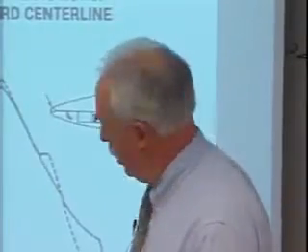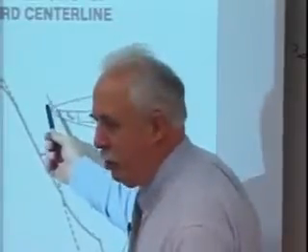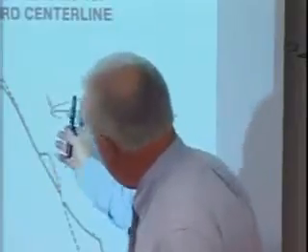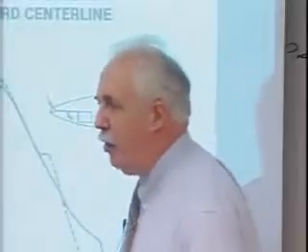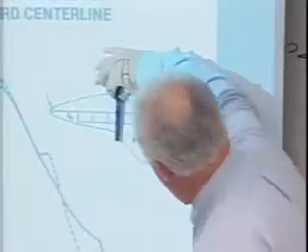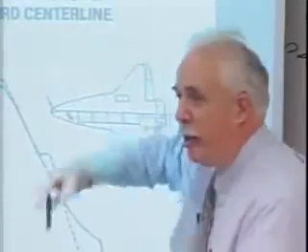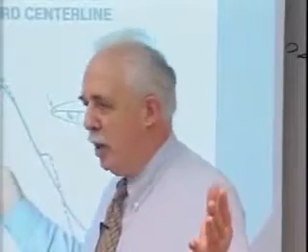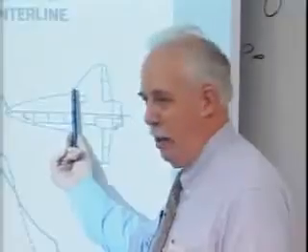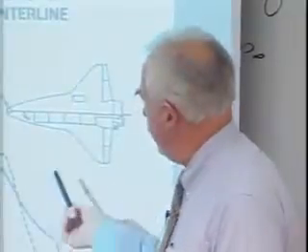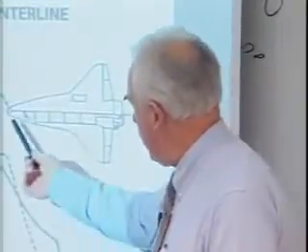Now, the flow field technology, we had a heck of a time getting from our starting solution, subsonic flow, which used one particular algorithm, to march supersonically down the vehicle. We succeeded in doing that prior to flying, and we were able to compute up to the point where the shocks from the wing intersect the shock from the fuselage, and then we had another subsonic region, and we weren't able to handle it. Now we can do that. But at the time we flew, we could only compute up to about here. Okay? Now, this is not what you'd see in the journal. I'll show you one you'd see in the journal here in the middle. This is right behind the carbon.